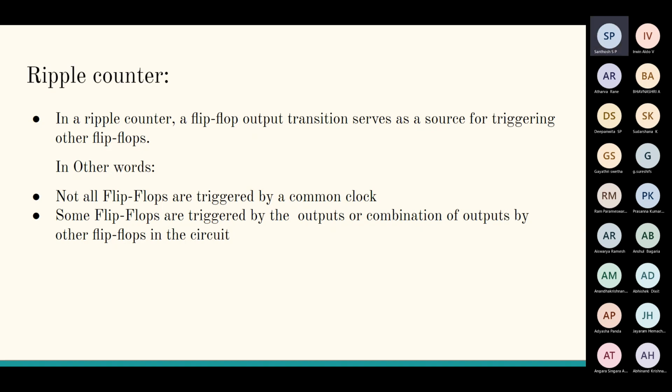So we can see that different flip-flops will have different clocks. That's why these flip-flops are not synchronous with each other, because they don't have the same clock. So they are called asynchronous circuits. Now we'll build an asynchronous circuit, and while building, the concepts will get clearer.